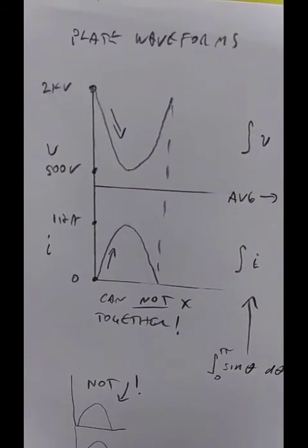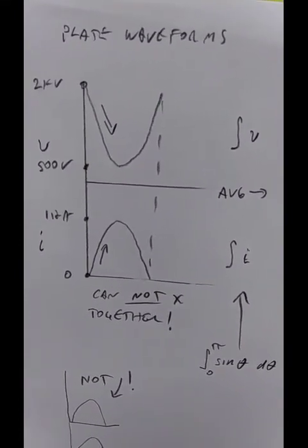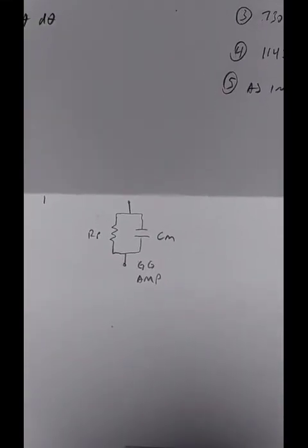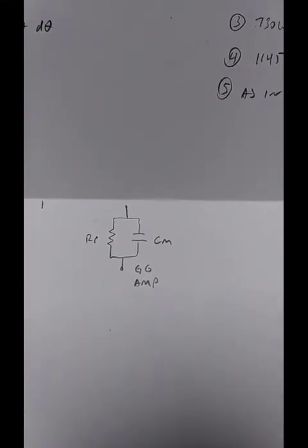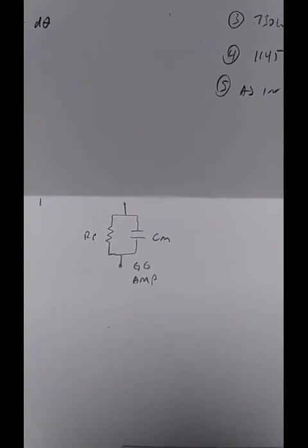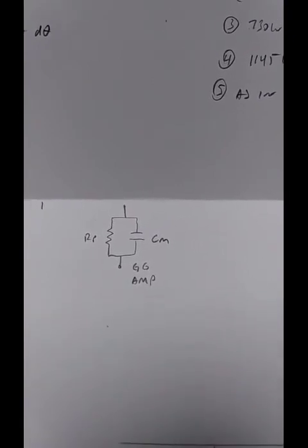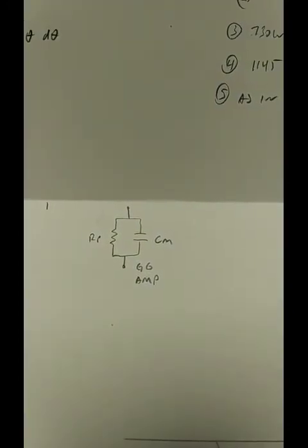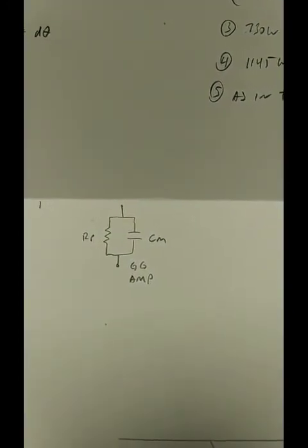So that capacitance doesn't play a part in amplification. In fact, it does just the opposite. It attenuates. The effect of Miller there is to change that plate resistance from the ideal value of 2750 from the datasheet to something else. And that something else is a complex impedance. Most of the part of designing an RF amplifier is dealing with those complex impedances.